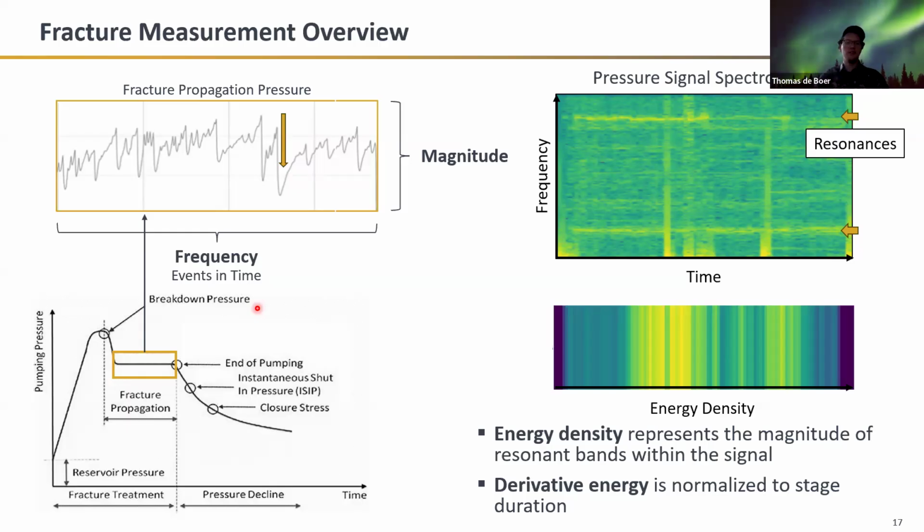I mentioned very briefly a bit on polarity analysis, but in tandem with this we've been developing techniques for processing microseismic data and using those microseismic data to get an idea of the where. So there is an integration that can be done there, not just to validate, but also to be used in tandem.